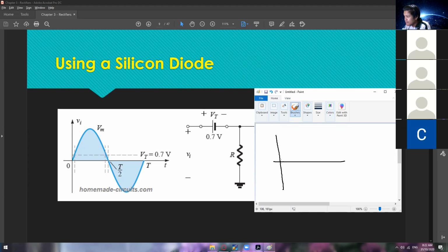So it will not conduct before it reaches 0.7 volts. So this is I, and then this is our voltage. It needs to reach 0.7 volts first. So 0.7 volts, of course, it has a delay, and then positive. And then another 0.7 volts at this point, and then negative. And then another 0.7 volts, positive. Another 0.7 volts, negative. So bear with my drawing since I'm only using a mouse.